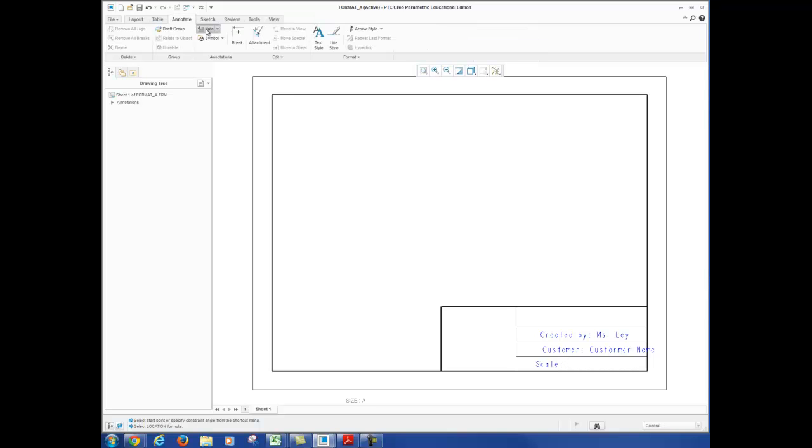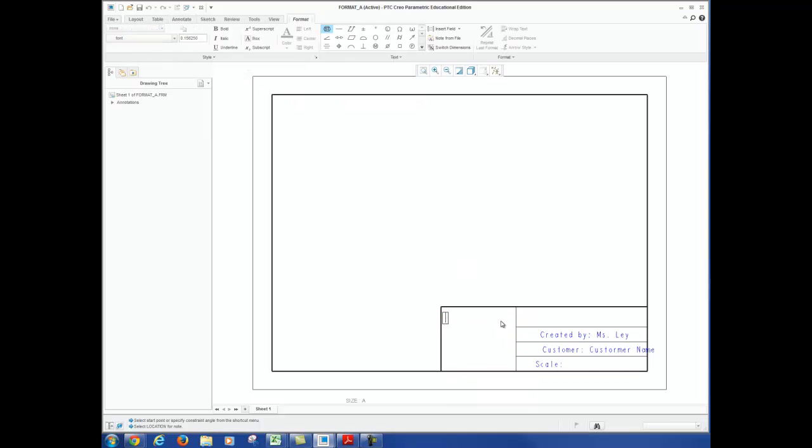In the side box, I'm going to generate a new note. The last note, go ahead and type in tolerances. Press enter. And we're going to start with our tens place. And so to create the plus or minus sign, you can find that in the symbol palette in the Format tab up here.